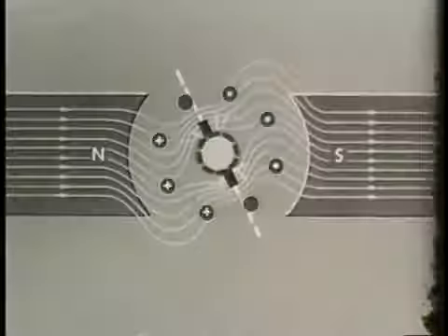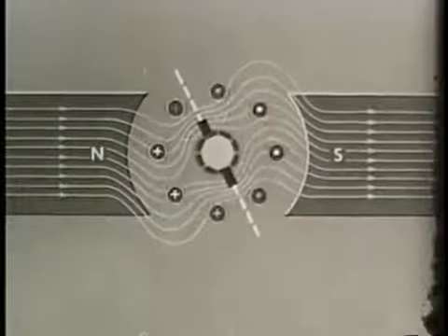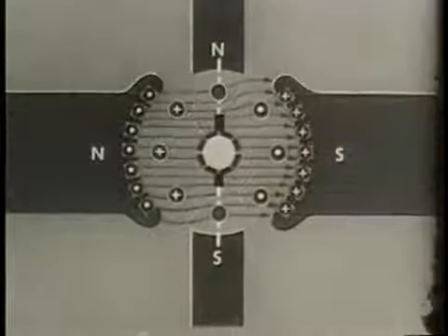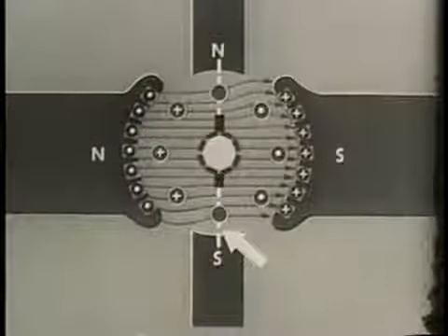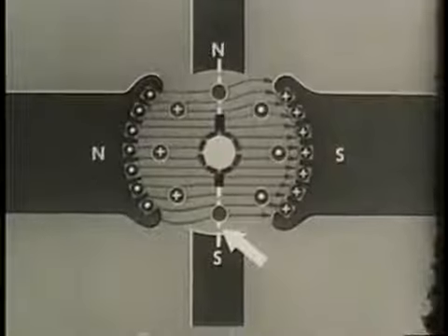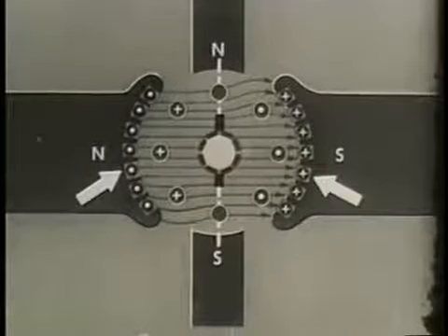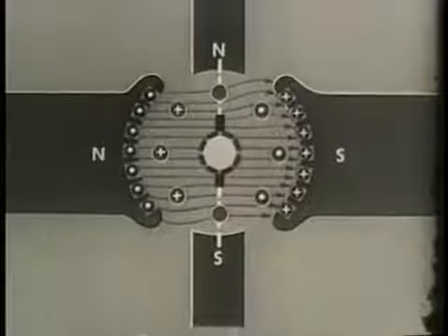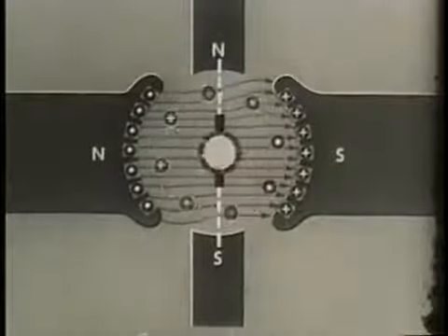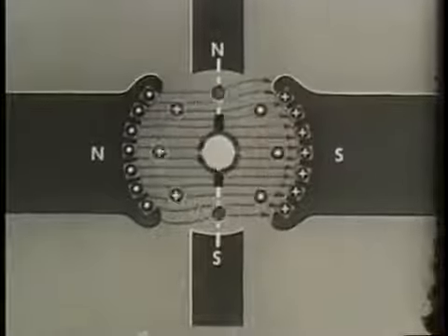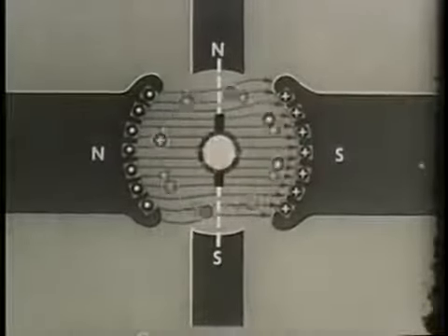In the motor, as in the generator, small interpoles between the poles of the main magnets are also used to eliminate the shift of the neutral plane. These interpole fields tend to oppose the fields created by armature reaction. The neutral plane is moved back toward its correct position. Also aiding are compensating windings, which carry armature current in the opposite direction to the current in the armature conductors. The neutral plane is thus maintained in its proper position. DC motors operate most efficiently when sparking is eliminated.